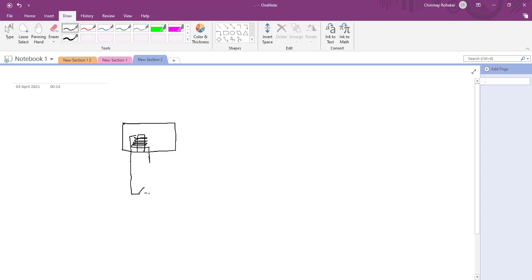So you can control whether or not there will be current through this switch. When you turn on this switch, the coil will get electric current, the solenoid will get charged, and it will create a temporary magnet. Over here you have another connection which is known as a common connection, right? Over here you have a metal plate which is connected to common.